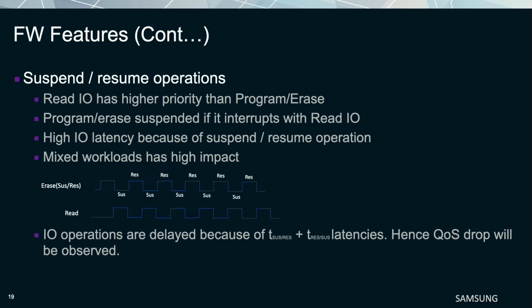This was what I was talking about, the suspend and resume operation. So in SSD software, read has the highest priority in terms of IOs. Read IOs have higher priority than program and erase. Program erase suspend interrupts for the read IO. So let's say a program or erase operation is going on and a read IO comes, right? So it will suspend. But this suspension will have some impact.